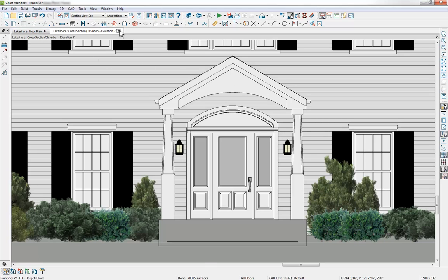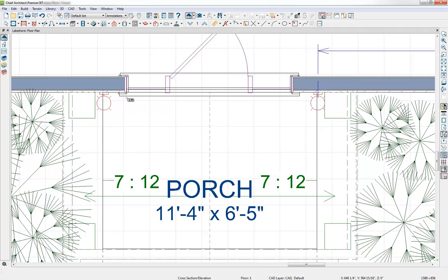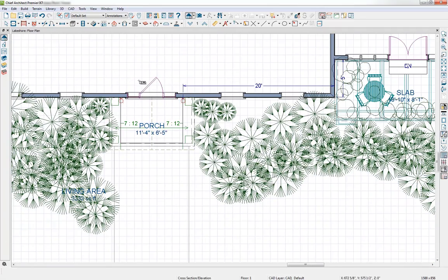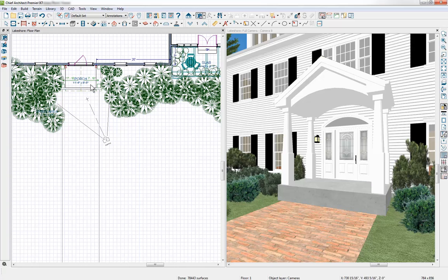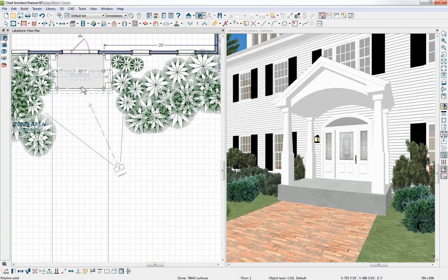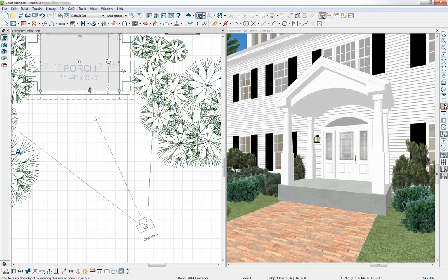And I'll close out of my elevation view. We'll get back into a 3D camera using that full camera. Just click and drag towards your focus. And now we have our curved ceiling applied. And I can select that and bring it out slightly, however you'd like it positioned.